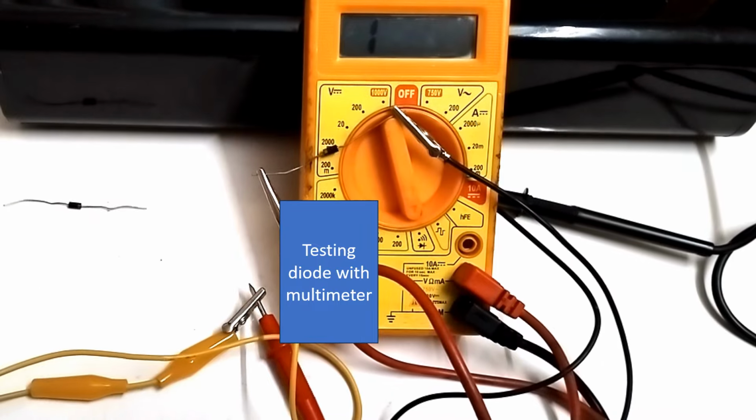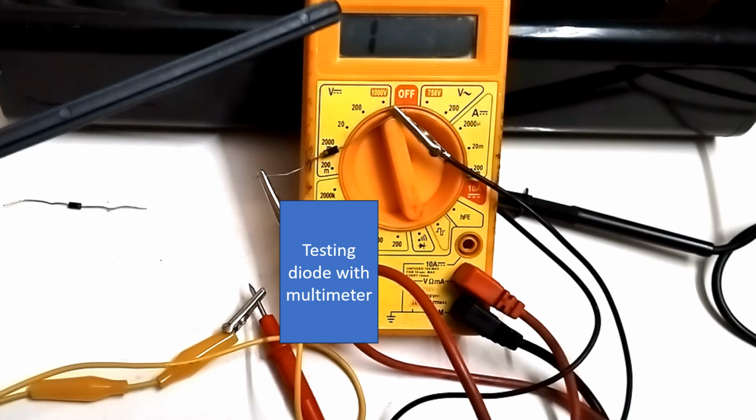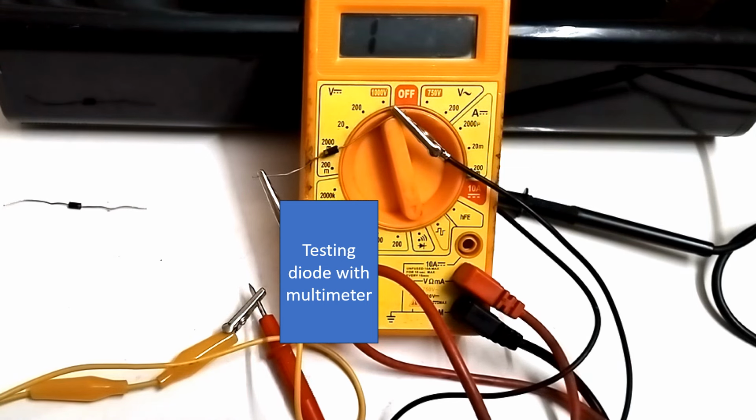Now the connection of the diode has been reversed, and you can see that what is shown is 1. 1 in this multimeter means it is beyond the range. It is not measuring that. So that is because this is reverse biased now. When the diode is reverse biased, no current flows across the diode till it reaches the breakdown voltage or peak inverse voltage which we discussed in the beginning.